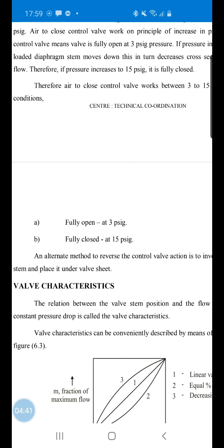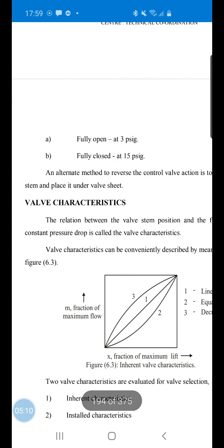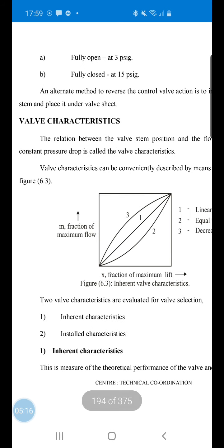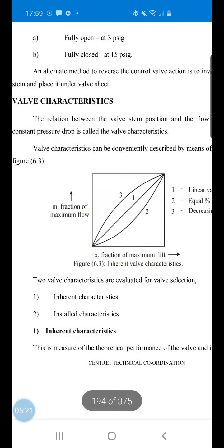So these are all the valves for process control. We know that the instruction or signals coming from the controller go to the final control element. These control valves are used as final control elements. These signals coming from the recorder cum controller through the comparator go to the control valve in terms of the pressure, and the output coming from the control valve is in terms of the flow. So this is how you can control the pressure, temperature, flow, level and composition.